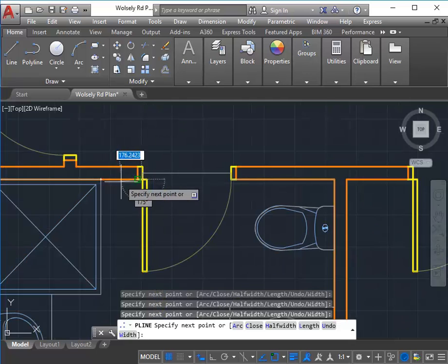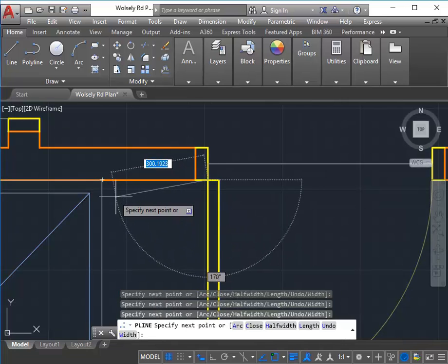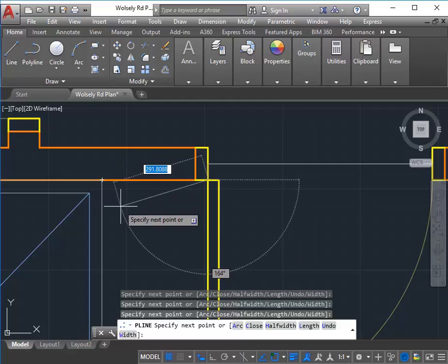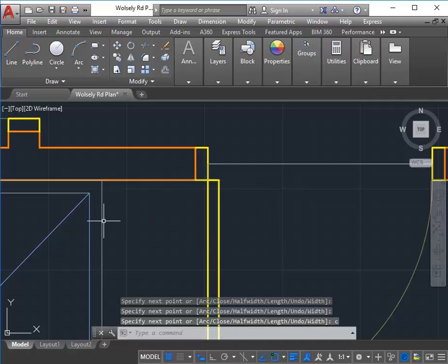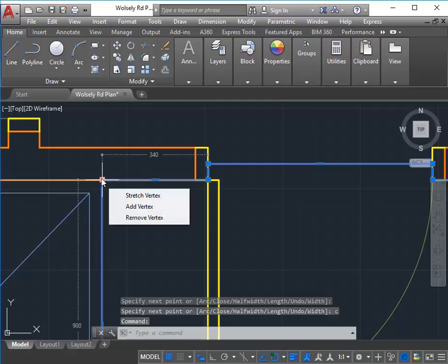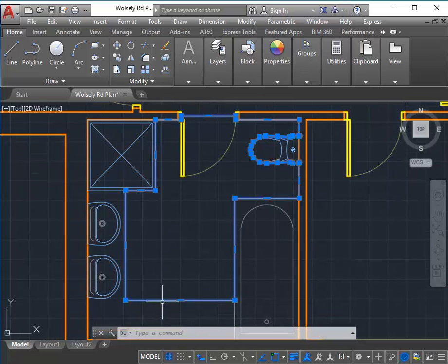And so just to give you some tips drawing polylines, try to remember where you start them. It'll sometimes show up, so you can see there the grip, or the little marker coming up on the point that I started on, but that won't always be there, so it'll help you if you remember. And then you can type C for close, and then enter to close it when you're finished. Right, so there's the shape that I've made for the hatch boundary.